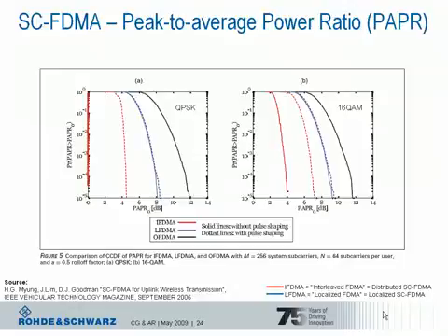This is different for single-carrier FDMA, especially for interleaved FDMA. For localized FDMA, which is the blue line and the mode which is used in LTE, the peak-to-average power ratio in case of QPSK modulation is around 8 dB and therefore 3 dB lower than OFDMA. For 16-QAM the difference is just around 2 dB.